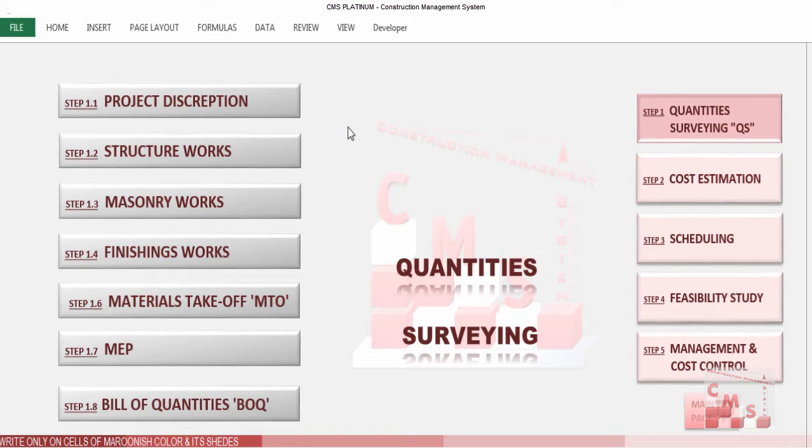We just give here in CMS indications for quantity surveying of all the subcontract activities, to give you as a construction company or as a main contractor a figure of what the cost will be for each subcontract activity, only as a figure for yourself, to identify and evaluate the prices or the quotations which you receive from your subcontractors.